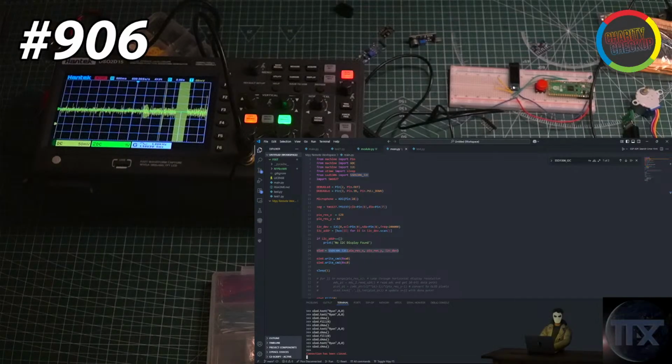Quick question. If I have an analog measuring device with 3 pins, voltage, signal, power, ground, how do I power it without wrecking everything? Yeah, you'll want to, of course, clip ground and power to the 2 pins, but you'll also clip the ground of the probe to the ground. And then the signal will just be the signal to the oscilloscope. So you have to have a power supply to power that. Okay, got it. But you can always use ground to the signal. Like ground of the oscilloscope to the signal of the device.